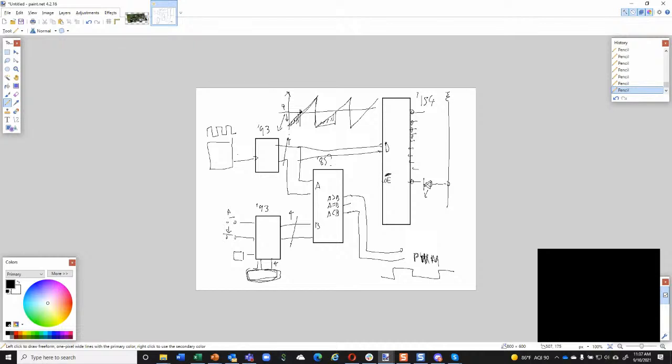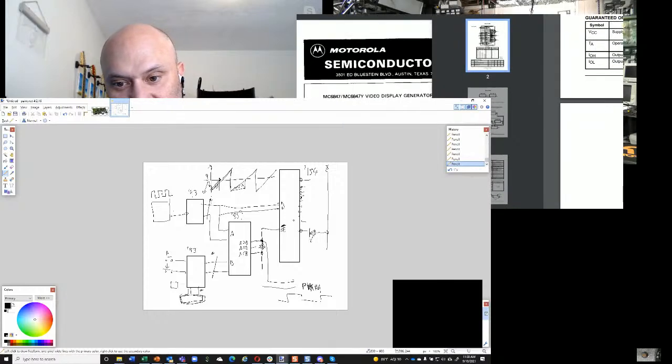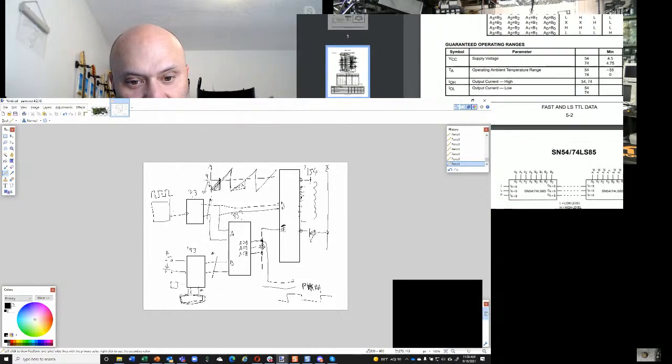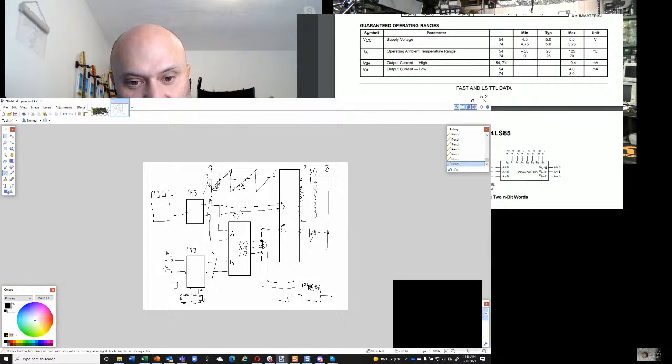Right. And so what I can do is say, only enable the output from the PWM. Actually, it would be the inverse, sorry. Let's delete that. It would be the inverse. So the LEDs would sequence one through the other while the output was high. And then as soon as it reached the set value and the output goes low, these turn off.